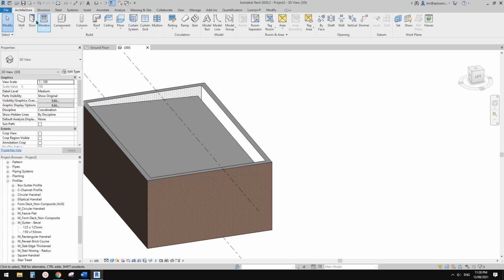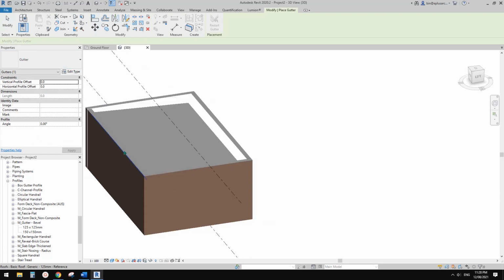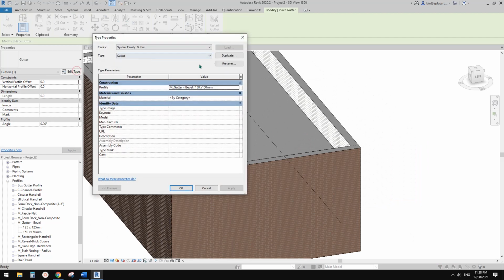And then we can just go on the roof gutter. So I'll just do a gutter straight away. So this is the previous one, the eave gutter, and then you can create a new box gutter this time. So change this to here. You will see this is 200, this is 300.